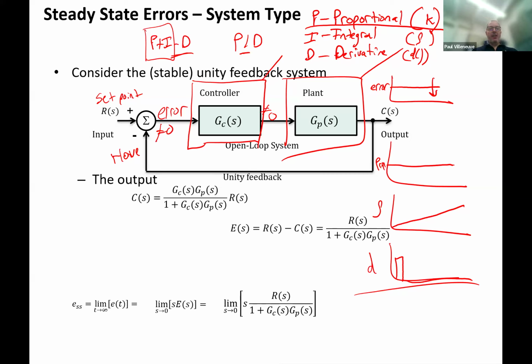All right, so here's our output multiplied by the transfer function of our input. And this is G over 1 plus GH. Notice that H is equal to 1 over here. So that's why you have the same numerator and almost the same denominator. My steady state error is calculated over here. Sorry for the mess. I just put a lot of material on here. So my error signal, the difference, is going to be calculated between what I want and what I have, R minus C. And so then I just move that in and factor it out.